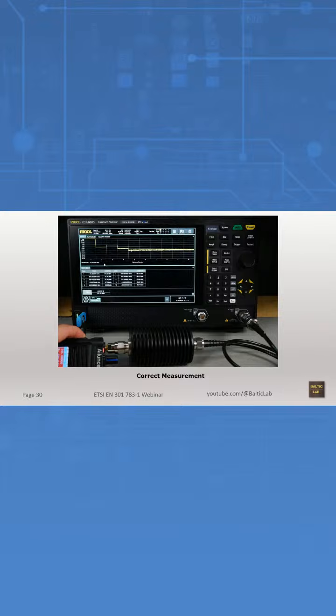So the only steps it takes is the harmonics. You need to be careful with that because it really just captures harmonics. We talked about spurious emissions also including any other emissions in between, so you really have to step through the entire frequency band. And how high do you have to go? Up to the 10th harmonic. So at 145 megahertz, you will have to go up to 1.45 gigahertz. Keep that in mind. Annoying if you don't have an option. Easy, like here, if you have an option that automatically averages, corrects errors, and applies correction factors.